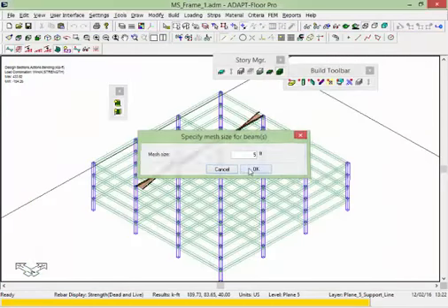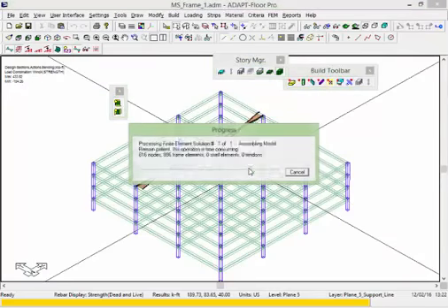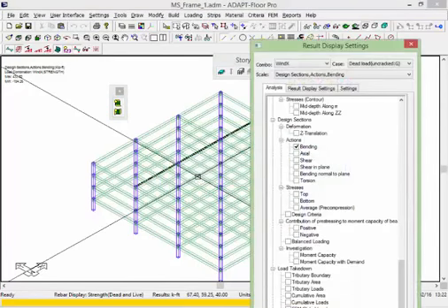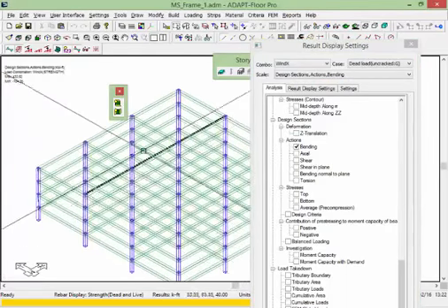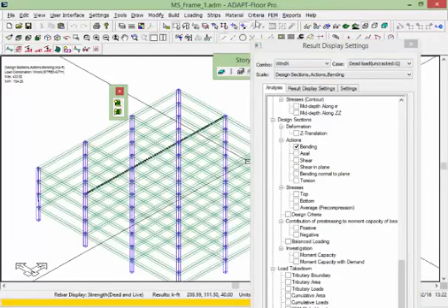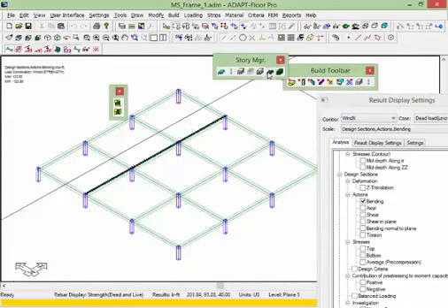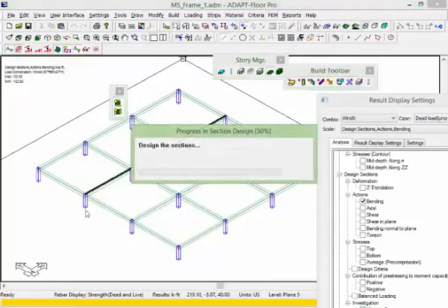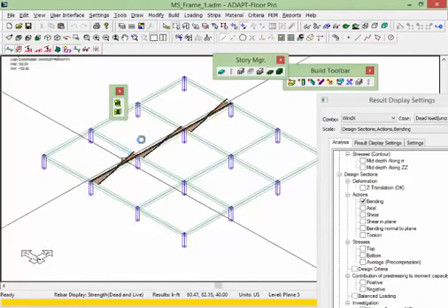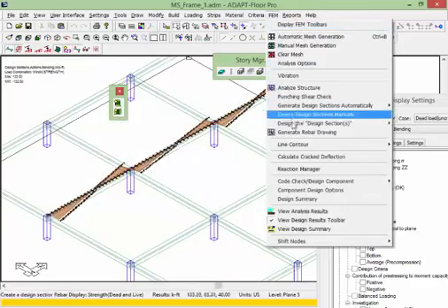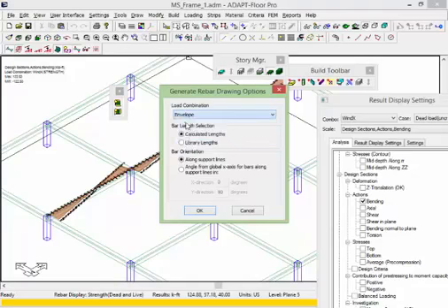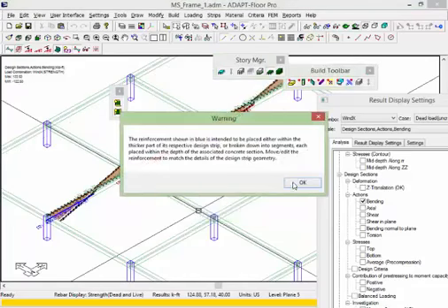And you can put support lines on all of the frame lines. I'm only showing it on one frame line, but you could get a comprehensive design for all of the frame lines if you added support lines for each one. And we'll go now to single level mode at the roof level, and I'm going to design the design cuts along this level. So we get back to showing those moments. Now if I go to FEM, generate rebar for envelope or for WindX, it doesn't matter in this case, we'll say OK. The program now reports the reinforcement for this beam line.